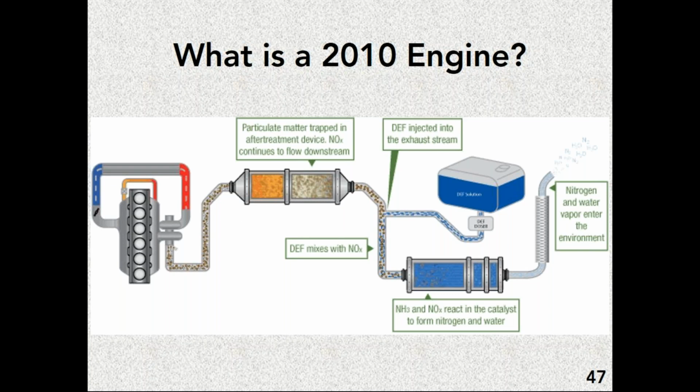You can see that in blue right here, the blue cylinder on the bottom. Now, that system is very special. It has a filter or catalytic bed that looks identical to the one you have in your catalyst for your regular vehicle. The difference is that it is coated with a special material that will only activate and reduce NOx when it's in the presence of pure ammonia.